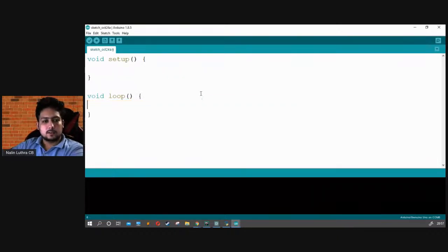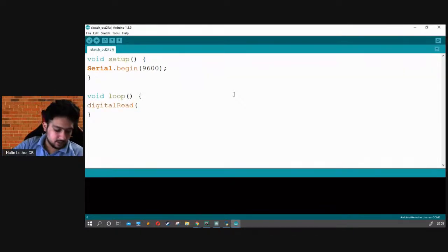Anyhow, guys, let's set this up. Let's start with Serial.begin and see the output together. We set it to 9600. We set it to digital read, so we have pin number 8 with us. So we go with 8, comma. Let's come on with that.